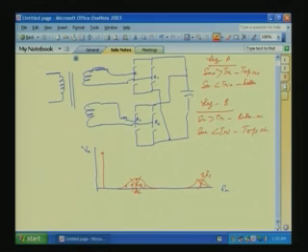We are using the triangle frequency Fc equal to 11 times Fm. So, all these harmonics Fc, 3Fc and odd multiples get cancelled.